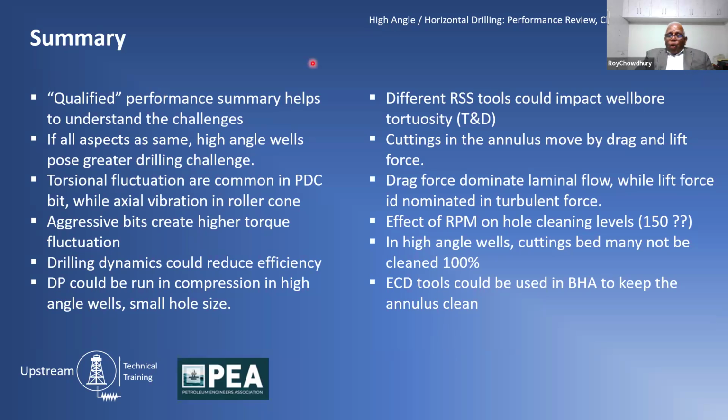Hopefully, you will get the idea that when you are analyzing performance, you need to qualify it with different factors that could affect the performance summaries that you are generating. Given all aspects are similar, high angle wells have a greater challenge, and those challenges could be dynamics, hole cleaning, swab surge, wellbore positioning.